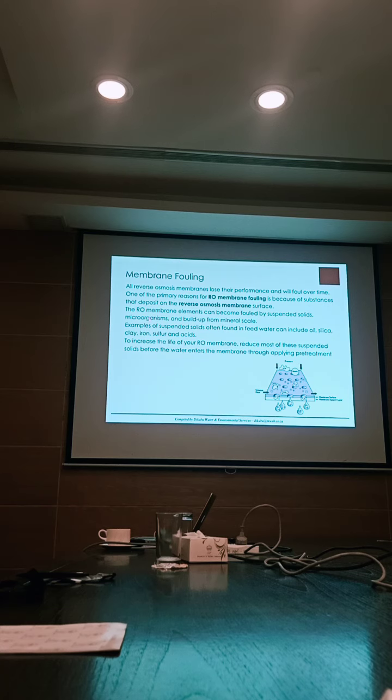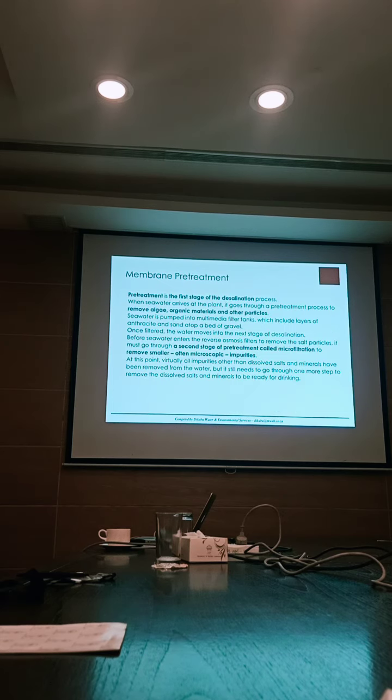Fouling on membranes is quite an important aspect. A lot of this becomes residual that ends up in your sludge or your precipitate or your material for disposal, your solids to call it that. And there are various ways to manage fouling, etc. Like I said, pre-treatment is quite important. Again, pre-treatment is going to generate some more material that you need to dispose of and manage.